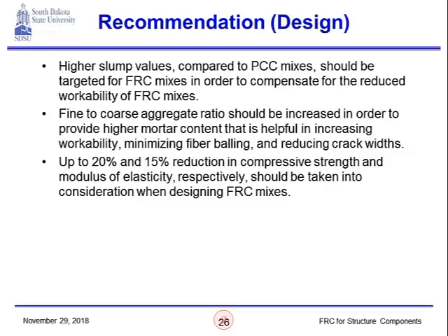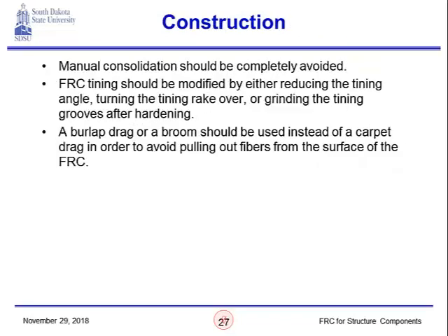And these are based on some of the literature studies, basically. Up to 20% and 15% reduction in compressive strength and modulus of elasticity respectively should be taken into consideration when designing FRC. That's based on our study. As I said, other studies showed contradictory conclusions. That's based on our studies. And we think we should keep it in mind till further studies are made on this specific property so that we know the reason behind it and whether we can eliminate this reduction.